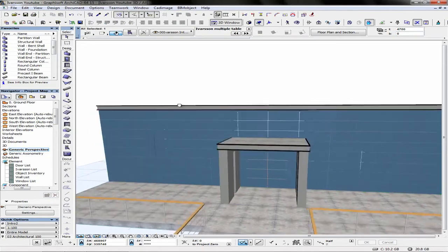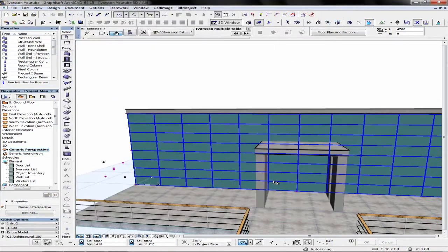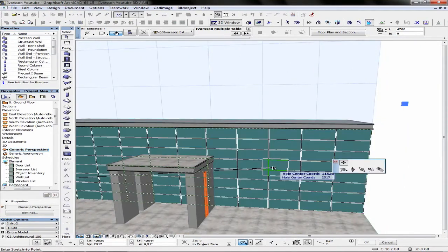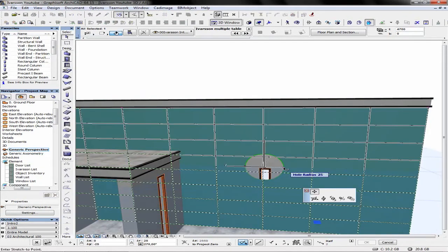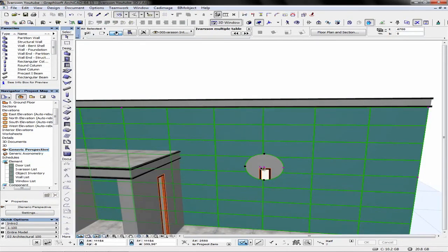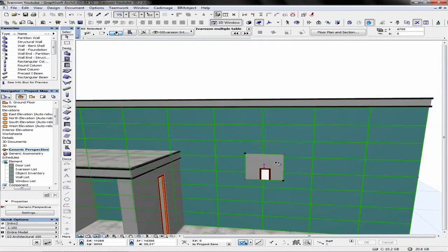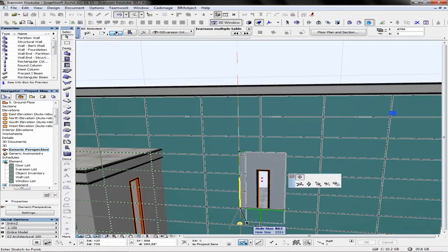So another good thing about this matrix object is we can have individual holes as well. So I know that I need 6 holes, and these holes can be different shapes. In this case, it's a rectangular shape hole. We have a control here where we can either turn it off, or we can simply do a circle here, and we can even change the radius of the hole as well. So what I'd like to do is just go ahead and turn this back on to a rectangular hole and quickly adjust that. And it's very, very quick to do.